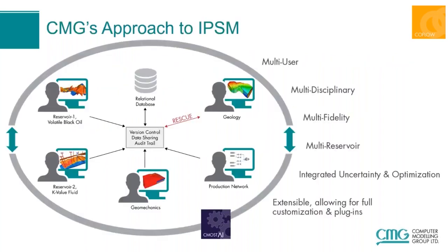Coflow solves these challenges by integrating the whole system. Now you have a multi-user, multidisciplinary environment where all the users, as you can see in the picture, are working on the same database, sharing information between each other. It is a multi-fidelity tool, so one of the reservoir engineers is using a black oil fluid in their reservoir simulation. Another one is using a K-value fluid.